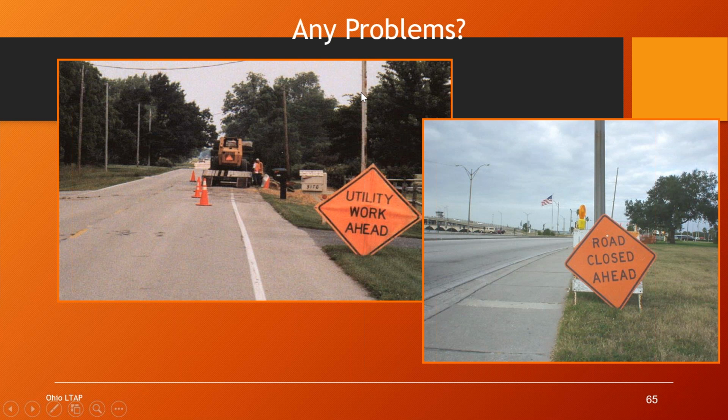And plus, when you see the utility poles at the edge of a right of way, well off the pavement edge, that usually means they're planning on the roadway to be widened in the future. And so this is not a low volume road. It's a higher volume road. And as far as the speed limit goes, it could be 55 because, like I said, I know 55-mile-per-hour roads that are much narrower and have no pavement lines.